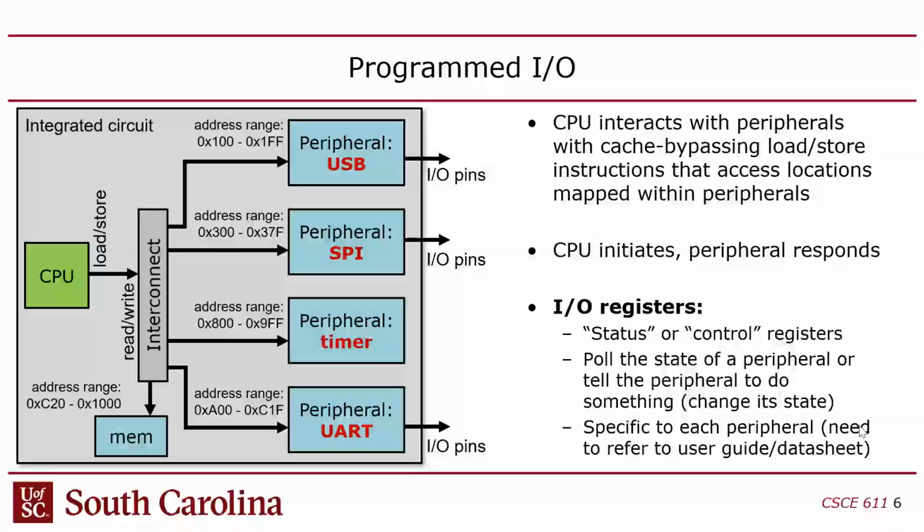Like when you guys took 313, you were actually able to change these addresses associated with the peripherals because you were able to design the hardware. But if you have a fixed hardware system, like an ESP32 or an Arduino or an Intel processor, these are not changeable, right? Now, when you're programming in an operating system with virtual memory, you don't see these addresses because these addresses are all physical addresses. When you use an embedded system like the ESP32 or the Arduino, you can directly access these addresses with your user code, right? You're not blocked by the operating system like you would be with an operating system like Linux. You guys with me?